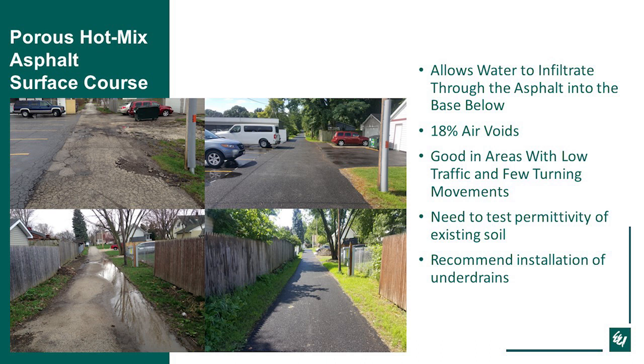Obviously, you want to make sure, because of that, the structure of the existing asphalt is very porous. It's not a good candidate for areas with high turning movements and high truck traffic. So in this case, it's just very few turning movements required, and it was just in a residential area with residential cars.